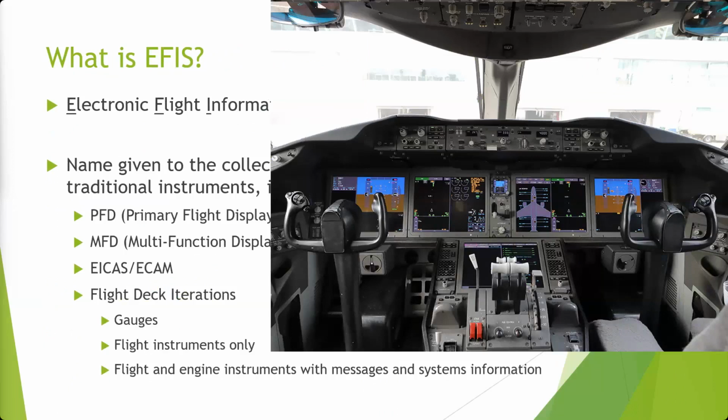Yep, I did that. Check that the circuit breaker is not... Oh, the circuit breaker's popped. So something in the pump caused an overcurrent. We're going to leave that off. Now what do we have to do to make sure that the plane's still safe to fly? And there might be other steps.